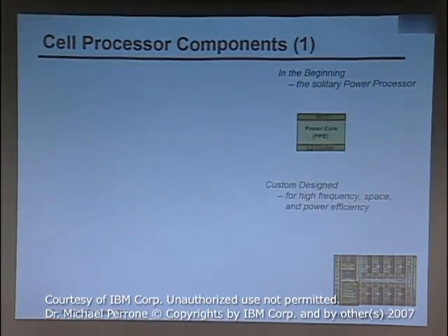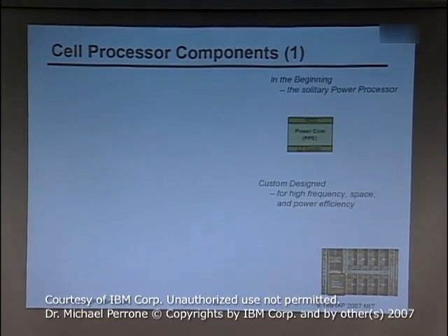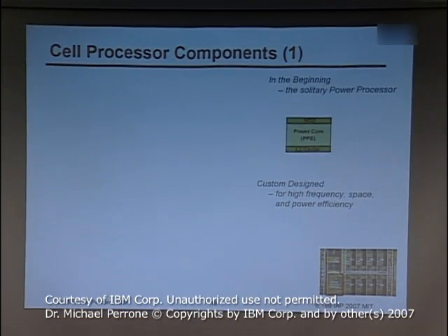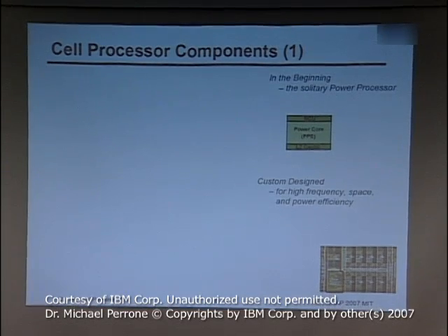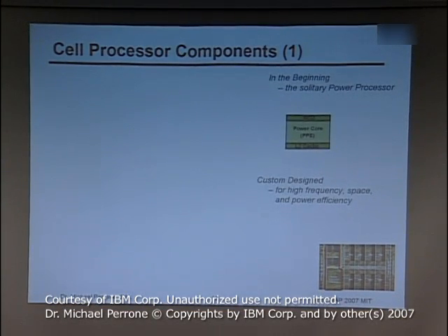All right. This is the PPE that I mentioned before. It's based on the IBM Power family of processors. It's a watered-down version to reduce the power consumption, so it doesn't have the horsepower that you see in, say, a Pentium 4 or even a Pentium. I don't have an exact comparison point for this processor. But if you take the code that runs today on your Intel or AMD, whatever, your Power, and you recompile it on Cell, it will run today. Maybe you have to change a library or two, but it'll run today here, no problem.